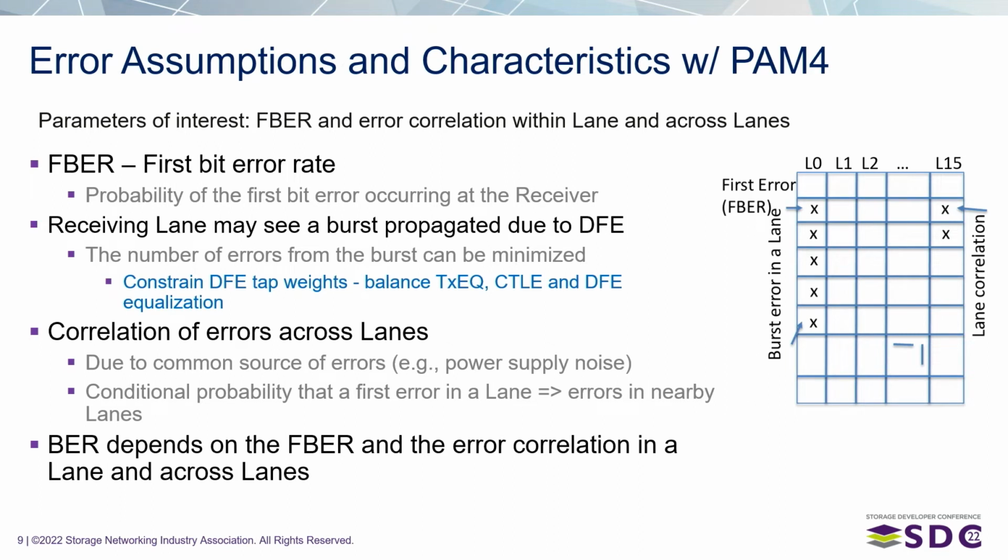So given that we're getting a lot of errors so far, PCI Express for the last 5 generations were all with a bit error rate of 10 to the power minus 12, which means that every 10 to the power 12 bits you can get 1 bit in error. With PAM4, those numbers are many orders of magnitude worse, right?